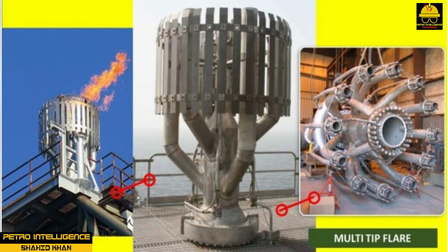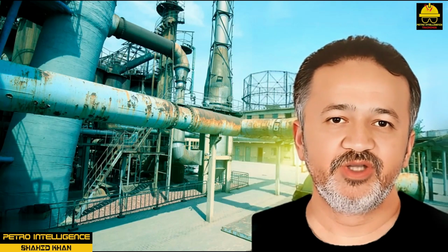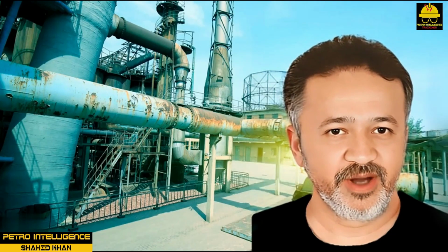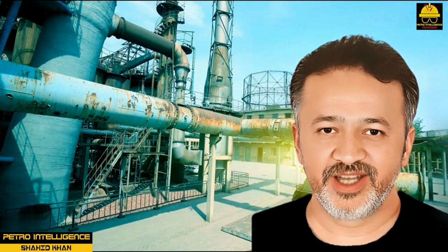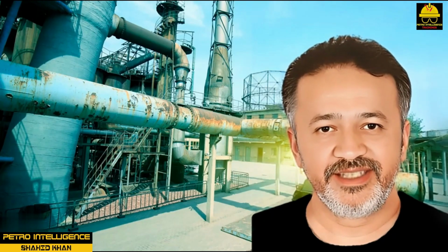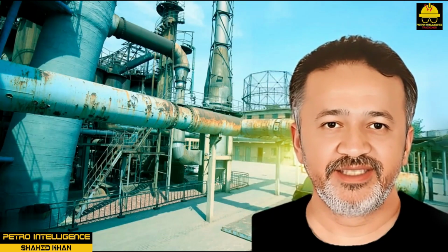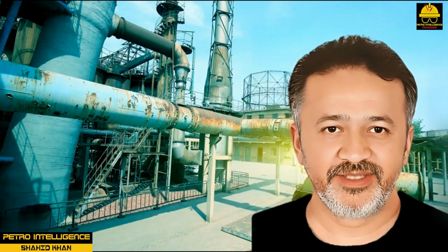The flare tips are equipped with pilot burners to ignite the gas as it flows from the tip. These are always burning, but if one goes out, it can be relit from remotely located flame front generators. Air and natural gas are connected to the flame front generator and are admitted in controlled amounts to form a combustible mixture that flows to the pilot burner through a small, 1-inch diameter igniter line. A sparking device in the mixing chamber ignites the gas-air mixture, and the flame travels through the line to the pilot and lights it. Separate natural gas lines supply the fuel to the pilots.